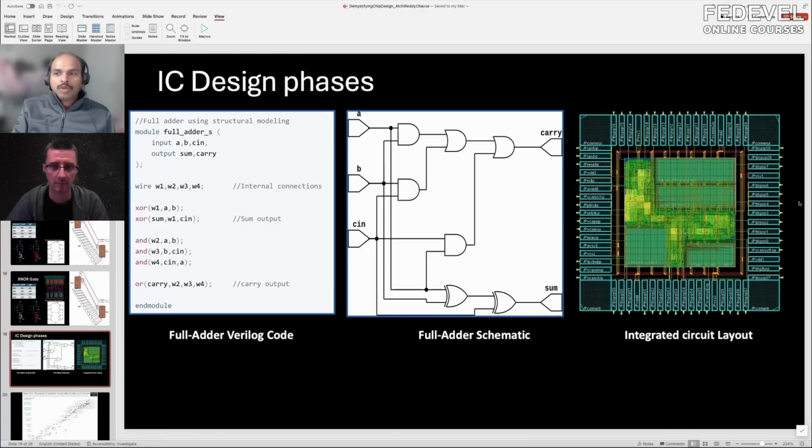So these input output structures operate at both voltages. When they're interfacing with the external world, that part of the circuit operates at 3 volts or 2 volts, and then it reads the signal and steps down into a digital equivalent of it, at a 0.7 volt, 0.75 volt level.